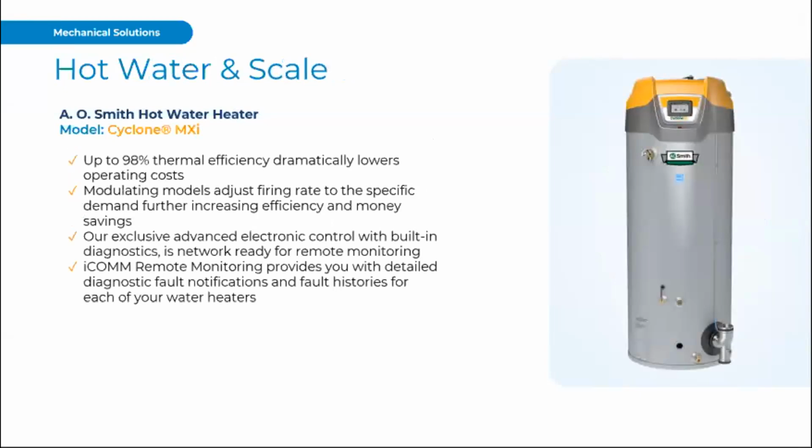In terms of our hot water generation, gas versus electric is going to be an early on design conversation. We do see quite regularly gas still in Ontario, but regardless, you're going to be looking at something with increased storage, because as we're going to get to later in the presentation, the kitchen areas, if present, can very much so affect your design for the flow rates in this type of facility. If there's a food service and prep area on site or dishwashers on each floor, that will drastically affect your dump loads that are required for these projects.